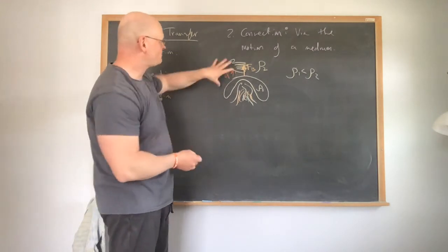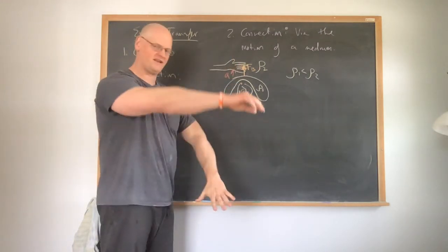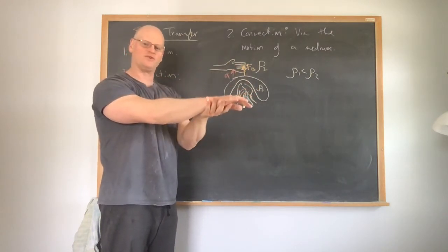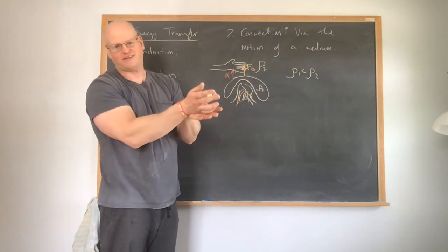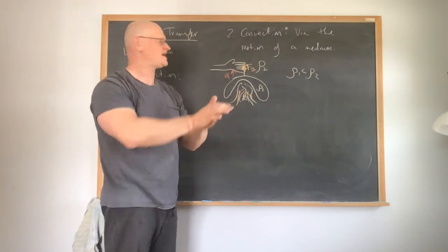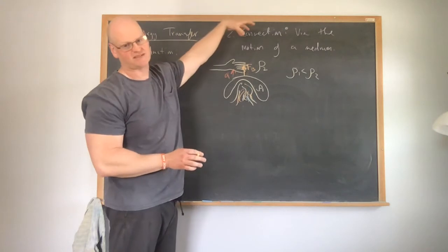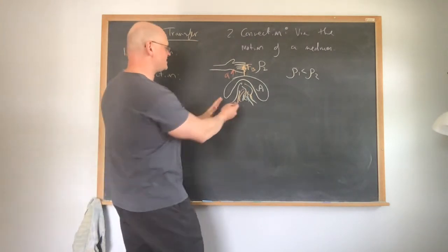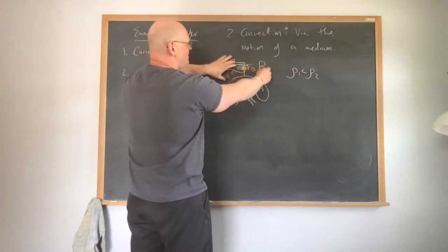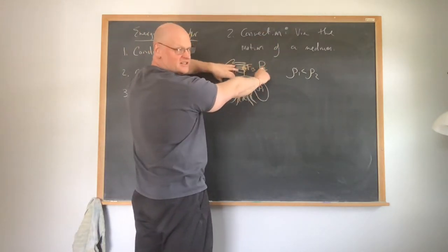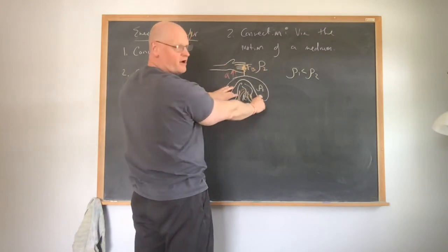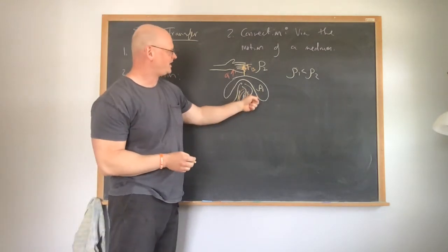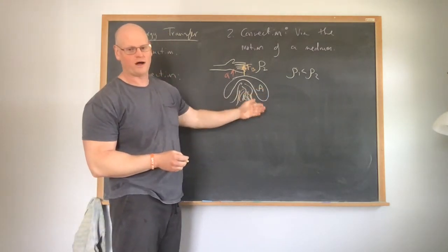Again, this density is now less because of that increased temperature via the fire. So this pocket of air is going to accelerate upward, and it's going to accelerate past my hand, and as it does it is going to transfer energy, actually via conduction in this case, because now the two are in direct contact with each other, but ultimately because of this convection of the air moving through. Now, this air is going to keep moving up, which means that this air here, which was at an initial density of rho 2, falls down into this location because it's heavier, so it's going to fall downward, heat up, reach a density of rho 1, and then go back through.